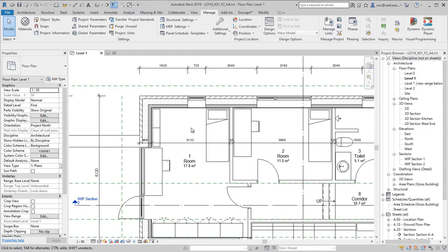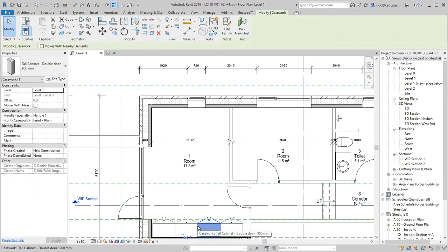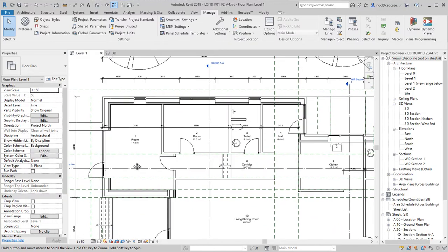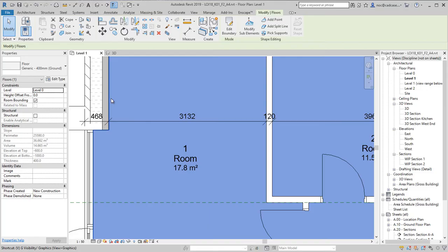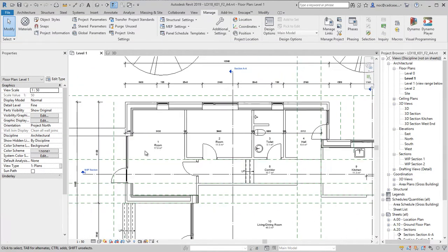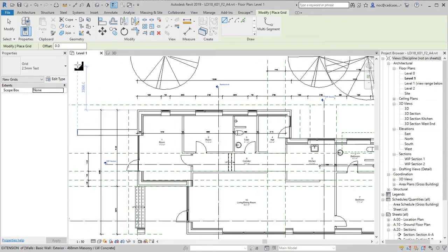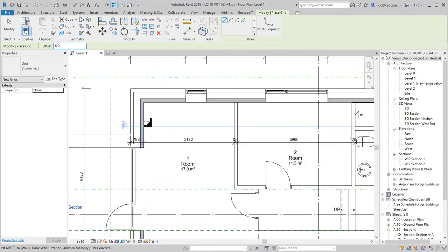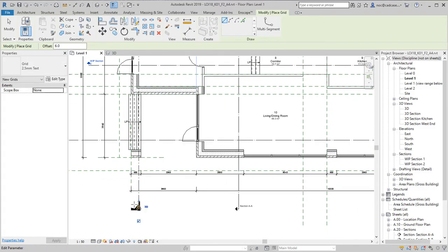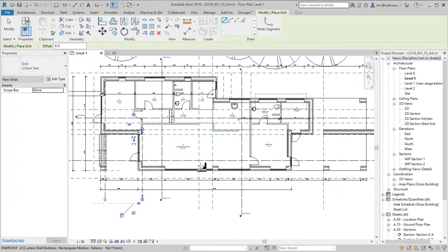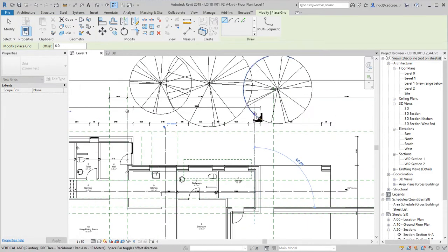So now we know that the construction of our external walls is made out of brick, and we know the sizes of those walls. We need to fit this into modules according to brick measurements. So a way to do that is to add grid to our model and lock the grids and our walls together, and then adjust our building according to the brick measurements. So I start applying grids to my external walls all the way around. And notice that I have an offset value of 6 millimeters from the inner side to my modular grid.